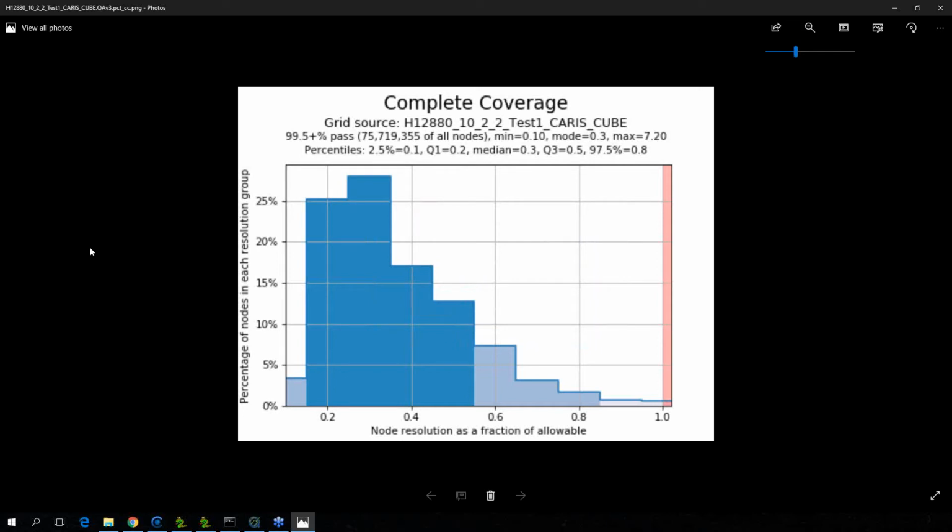With a density-based estimator like CUBE, you are giving it criteria and then telling it to grid at the highest supported resolution based on the data density. And so that's where the algorithm is determining what the resolution is. So I think that's where these graphs are going to be really important, right? Just to make sure that you're actually meeting those requirements.